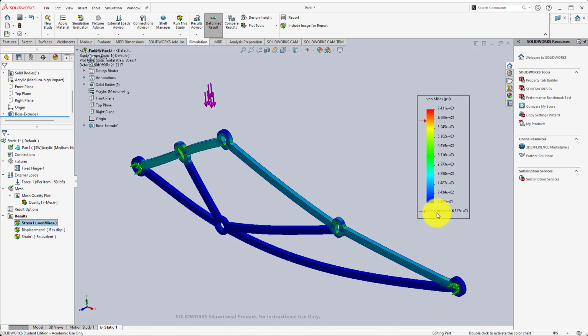We can relate that to the yield strength of the material, because when we pass the yield strength, we're going to assume this material is going to break, especially this acrylic, because it's very brittle. So it's not going to have a lot of deformation occurring after the yield strength. Once we get to the yield strength, it's going to be snap, crackle, pop for this thing pretty much.